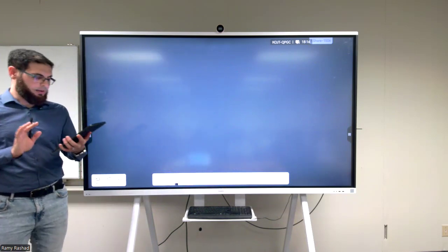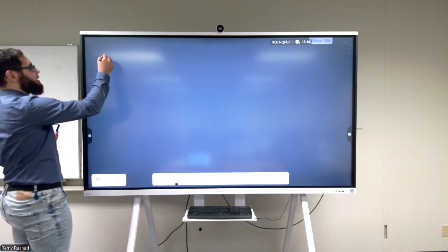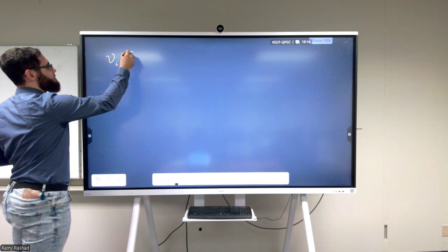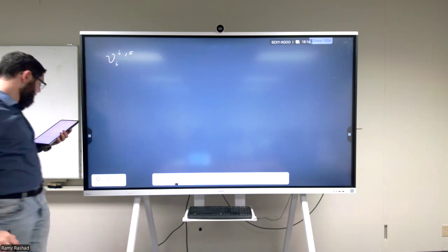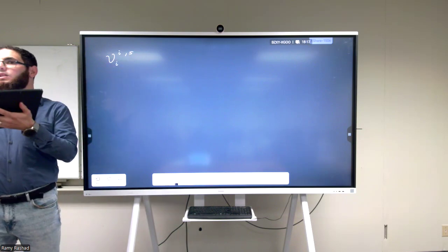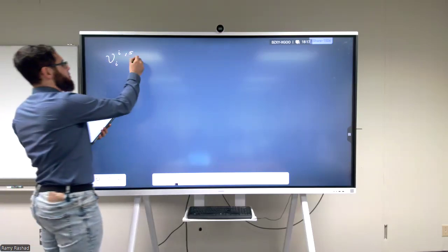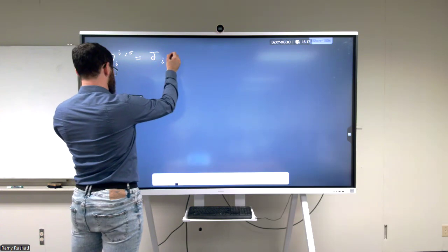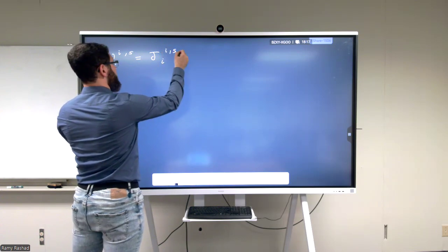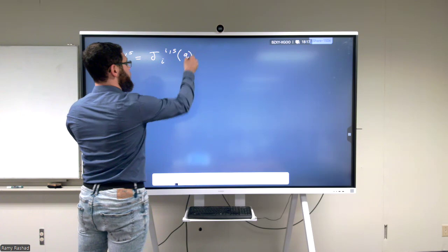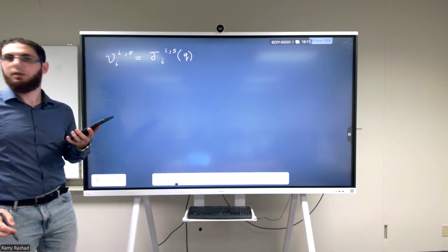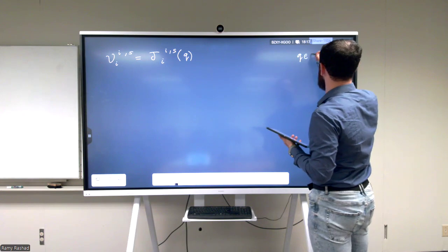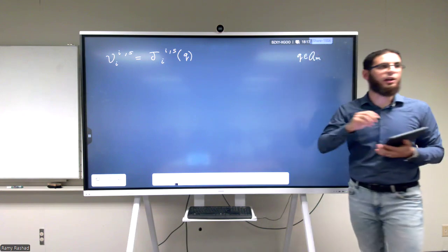Now, the key is writing the relative twist between any frame I with respect to S expressed in I. The key is to write it as some sort of Jacobian matrix I with respect to S expressed in I. It will be a function of Q. So we have two variables here. The Q is defining the configuration of the manifold.